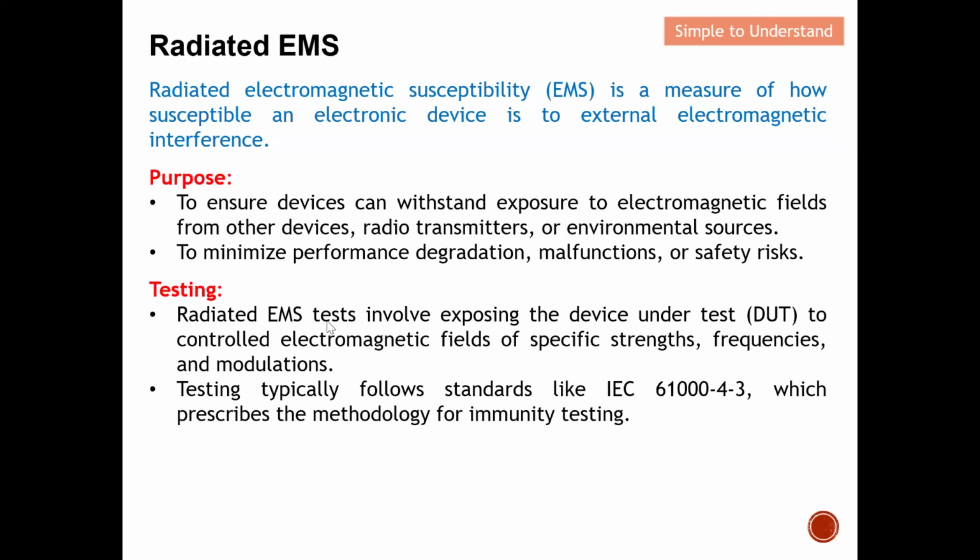Radiated EMS testing involves exposing the DUT to a controlled electromagnetic field of specific strength, frequency, and modulation. Testing typically follows a standard like IEC 61000-4-3, which describes the methodology for immunity testing. So basically, in short, again, you can always see the videos under the description for all this discussion.